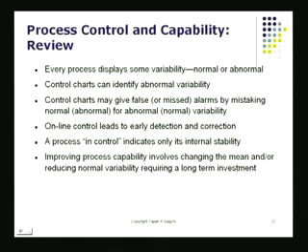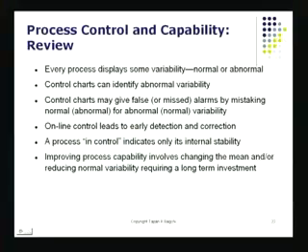If we get the process in control, if we remove assignable causes, what we are left with is essentially the process under the influence of chance causes only, which is the natural variation of the process. It is at that point you should try to make an assessment of process capability. Process capability is the capability of the process to produce output that will meet customer requirements. It's wholly within the tolerance that is tolerated by the customer. If there is a process like that, you have nothing to worry about.